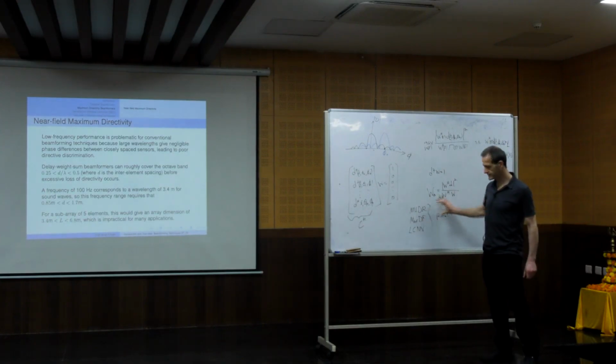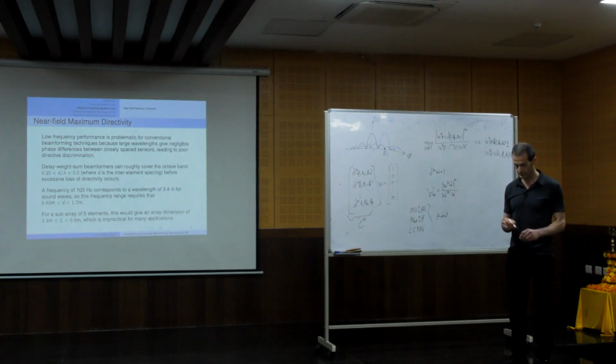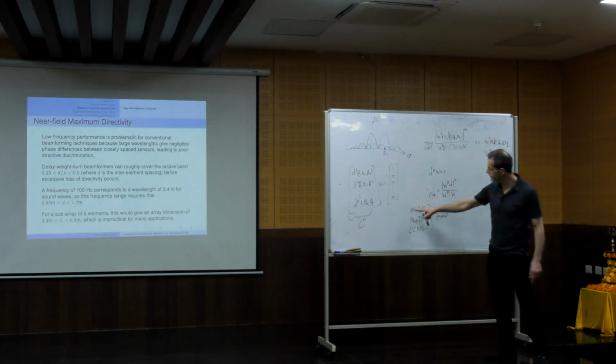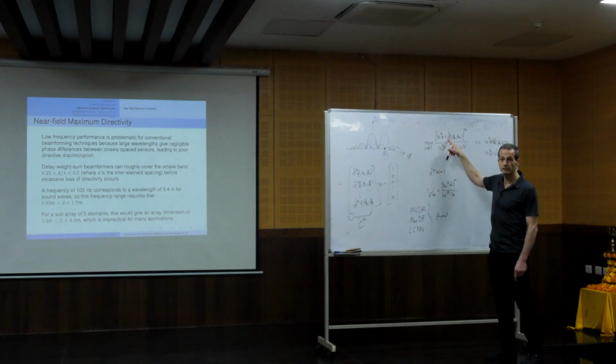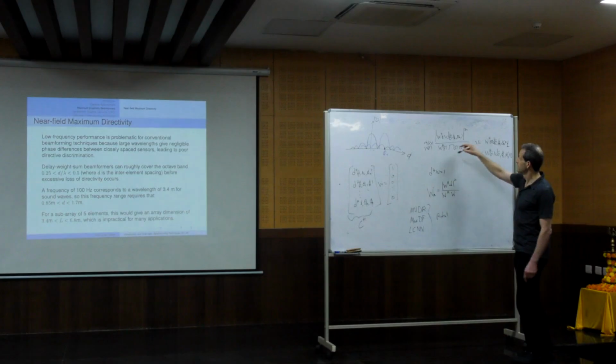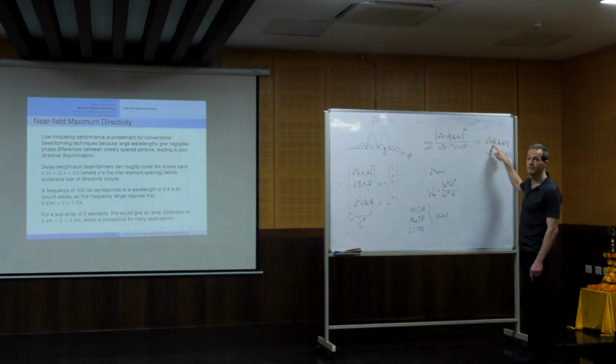And now, if we change this, instead of far field to near field, what do we need to change? Okay, so let's go for the MVDR. What do we need to change? Only this. So the propagation vector, or the steering vector, which you call it here, we need to change it to near field. So the constraint that it's equal to 1, it will be with D that is near field.